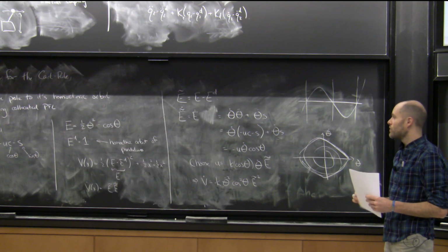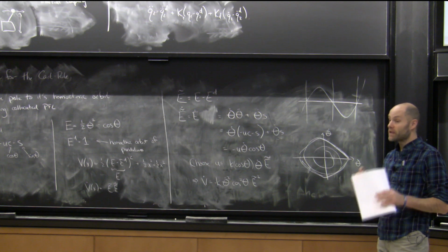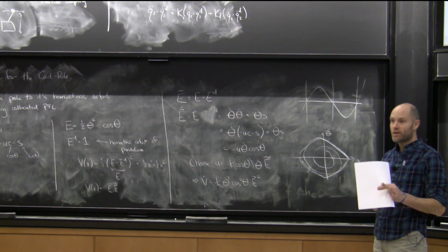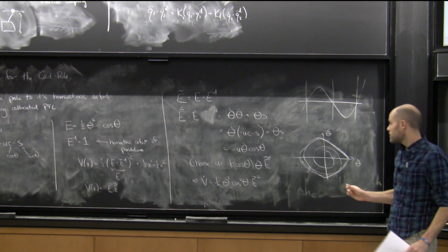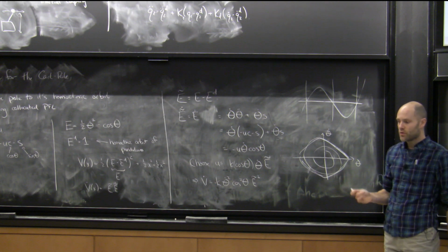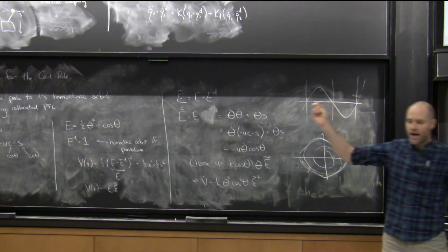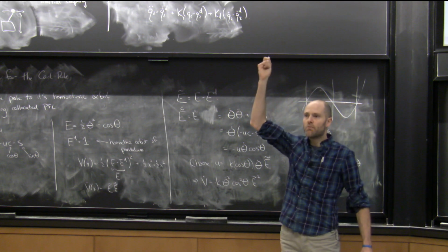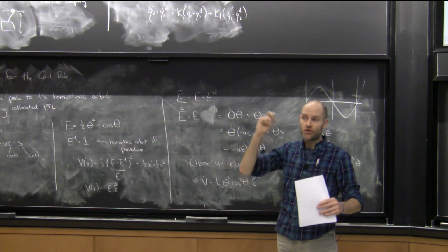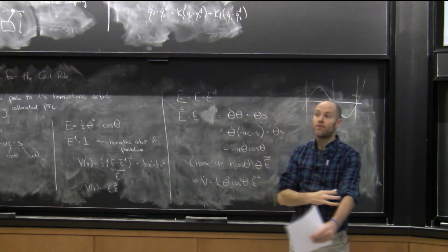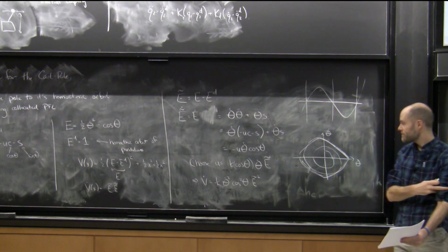And we're going to write an algorithm that will compute when it's safe to do that in the next lecture. So yes, exactly right. If your cart was moving at a very high velocity, even if your pole's at the top, you might not be safe to turn the LQR controller on. You want to be in the place where the linearization is good, which is closer to the 4-dimensional fixed point.